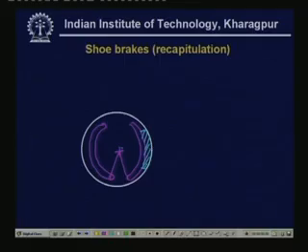So there is friction material, symmetrically placed again. This is internal radial shoes, and the force is applied here by some mechanism, and then these two calipers rotate about these two hinges, and then the friction material gets pressed and it develops the frictional torque.